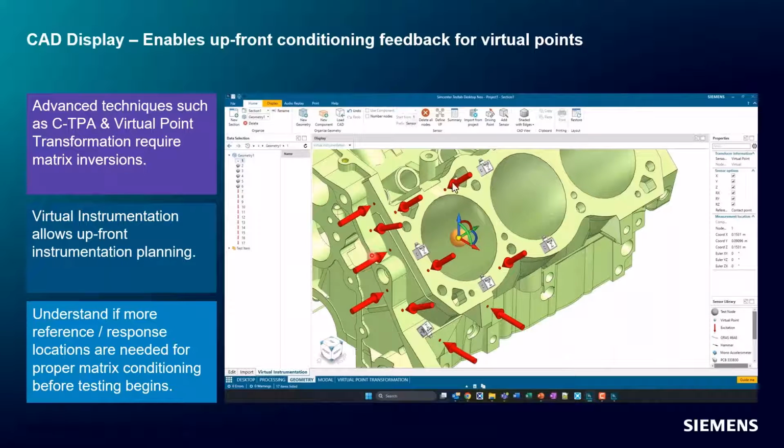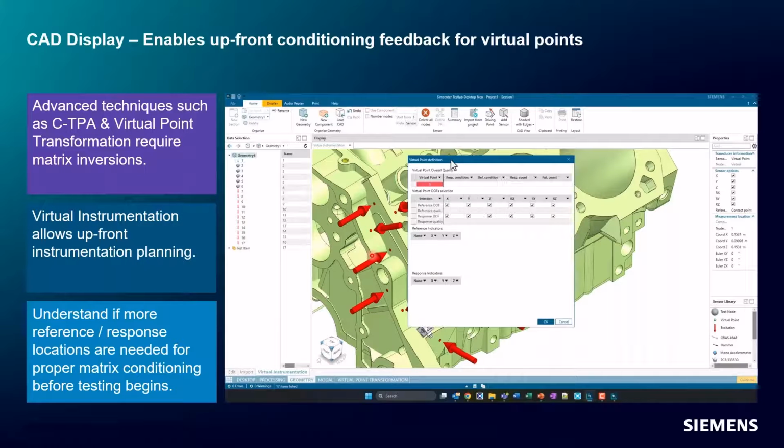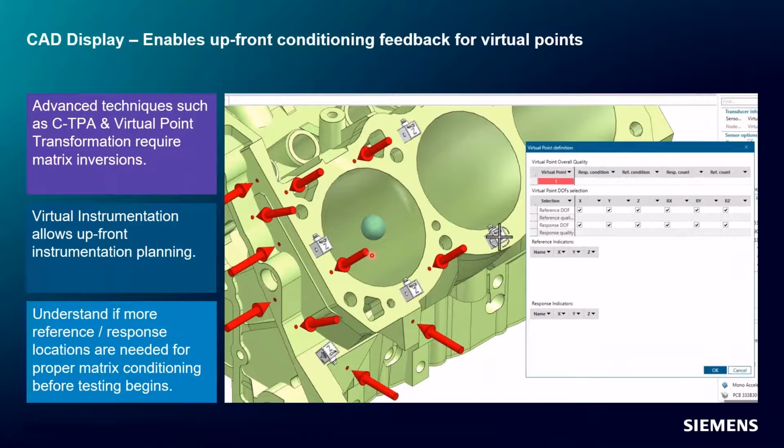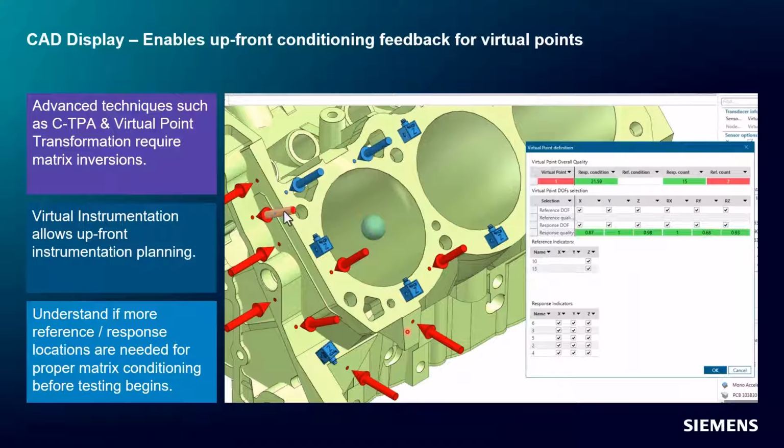So 3 translations and 3 rotations. And so we do that using a condition number. What you're seeing in this animation is that condition number being calculated for you as I'm adding the transducers, and it's all just based on the geometrical layout of these transducers. There's no data being fed here, it's just a geometrical calculation.